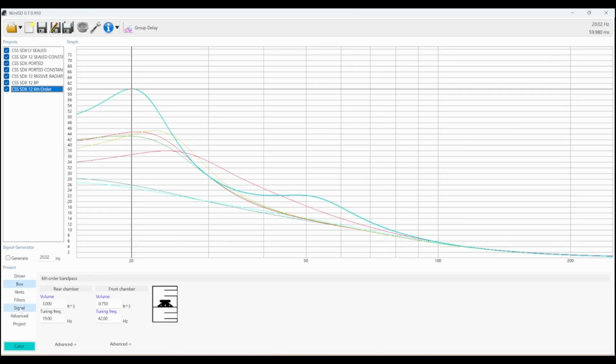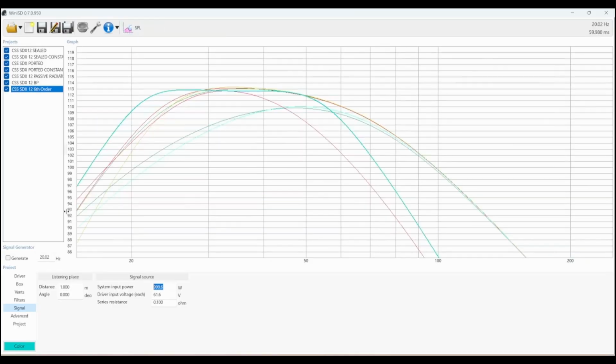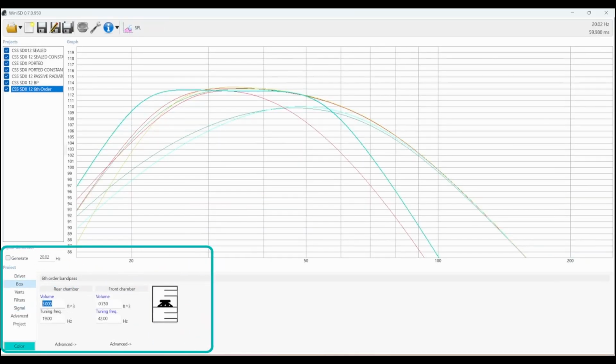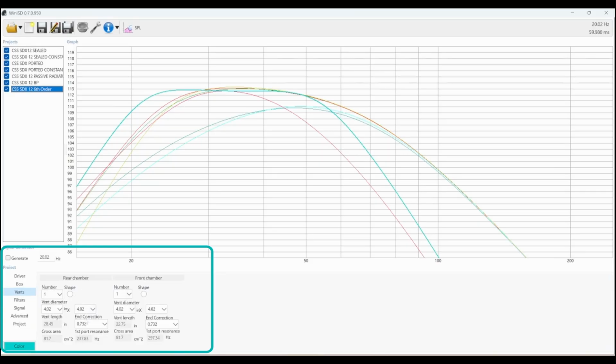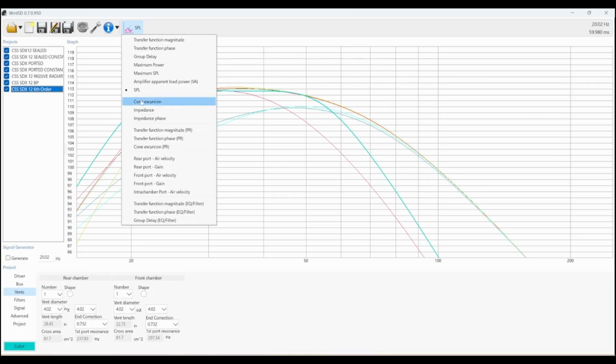The other thing is, it is relatively efficient on power, but it used a huge amount of airspace. If you took this same 3 cubic feet of airspace or so, plus the vent sizes that you have to accommodate, which we haven't even finished yet, then you may end up with a box that works better as, say, 2 subwoofers in the same space in a vented alignment. So sixth order may not be the right answer when you have plenty of power and plenty of subs to put in the same space.